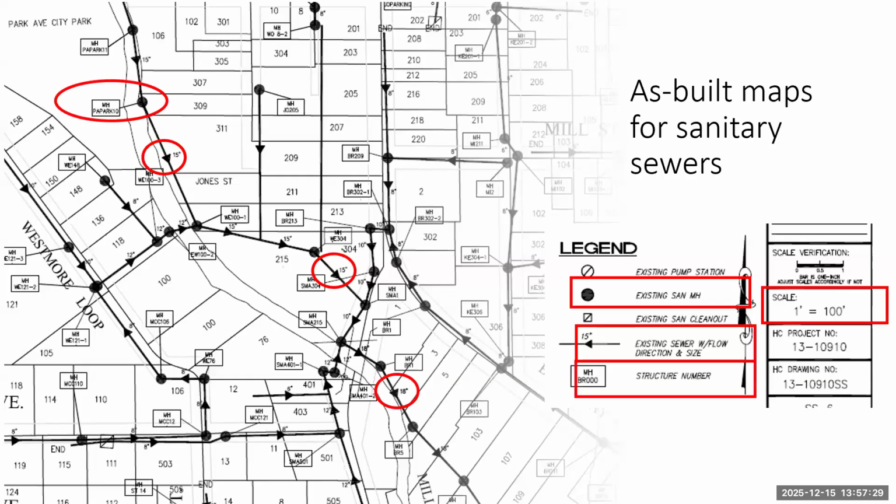Also, there's going to be a scale. It gives you, in this case, there's a 1-inch to 100-foot scale. So if you had 1 inch on the map and it's printed at the appropriate size, you could know that's 100 feet.